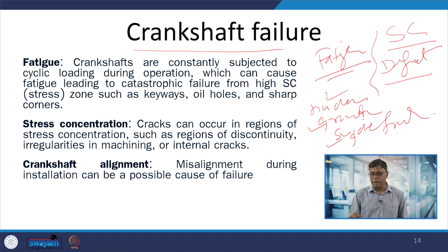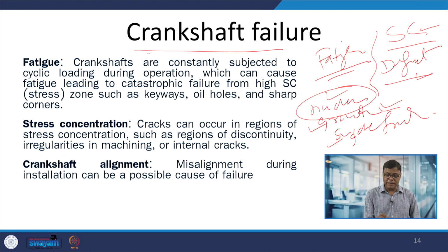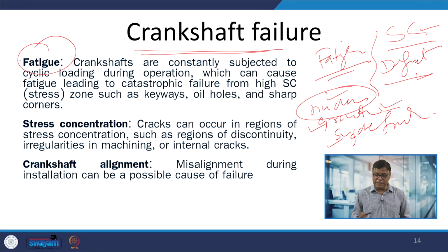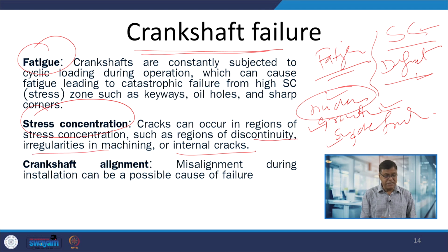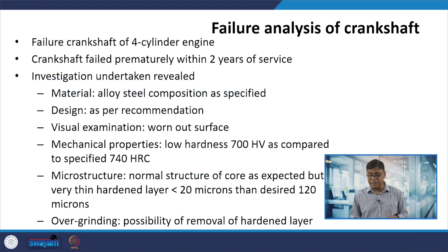If a component is having stress raisers or defects, then it does not require the nucleation stage. The cracks, meaning the crack-like defects, will start growing directly. Okay. That is why the fatigue life is significantly less. So, crankshafts fail primarily due to fatigue, and the failure tendency is extremely high when there are stress raisers. Stress raisers may be in the form of defects, discontinuities or machining irregularities in high stress areas, or the assembly of the crankshaft is not perfect and has misalignment that will be causing skewed loading.